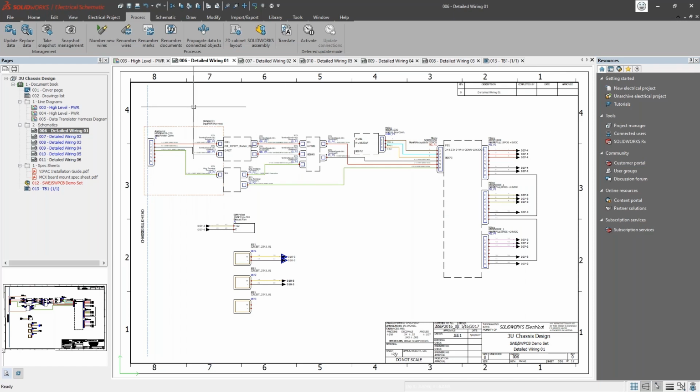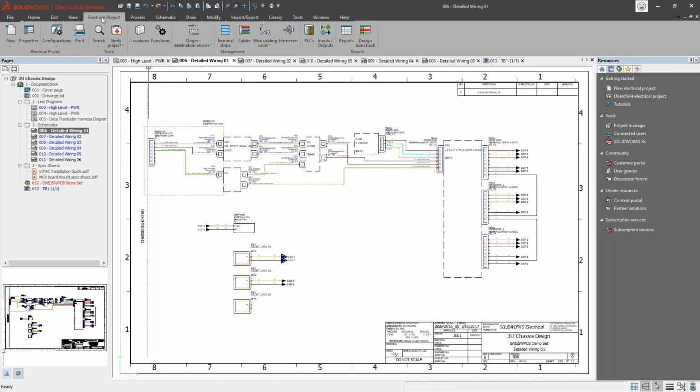So now that we have that information in there, the next thing we want to do is generate some reports. There are two different types of reports. We talked about that auditing capability, and of course there are the reports like to-from wire lists. There's the reports: bill of materials, to-from wire list, wire run list, whatever you want to call it. And then the design rule checks are things like your voltage drop for cables or a duct fill ratio.